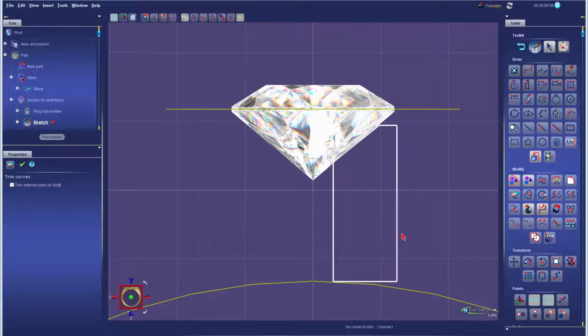Okay, let's also go ahead and add a little bit of a fillet to take care of those sharp edges. So we'll click on fillet. I'm going to use a 0.1 millimeter and highlight the curve just by hovering, and then round each corner. We just have to do the 3 outside corners. Validate that. And that's it for the sketch. Go ahead and exit.